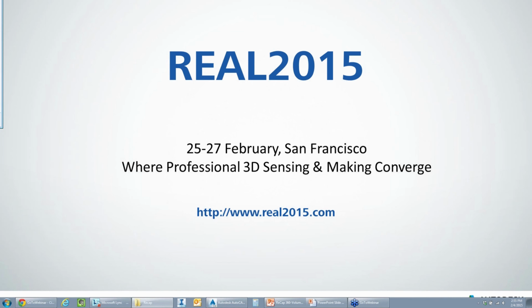All right. I saw a couple of questions. I can grab this one. People are asking if they need ReCap Pro to be able to import these point clouds. ReCap Pro is our scan-to-scan registration capabilities as well as survey control. Unless you're tying your stockpiles into a survey plane, you shouldn't need Pro to do this workflow. The free version of ReCap should suit you just fine.